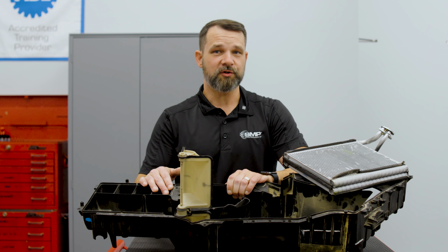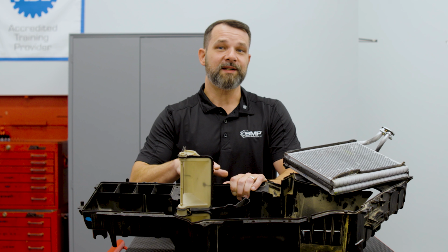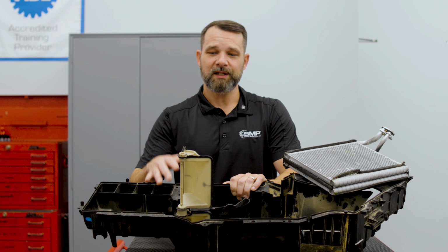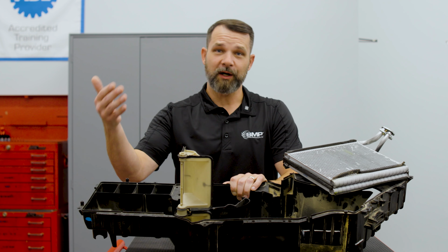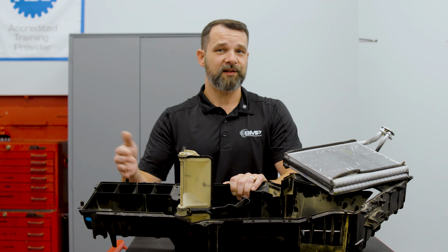But if you do have a vehicle in your shop that's torn down completely like the F250 we just showed you, this is something to always check. Double check the integrity of the sealing of the case. That way when you get those blend doors or air doors or whichever door you're replacing back in, we know that the air is going to go where it's supposed to go without any of that slippage.